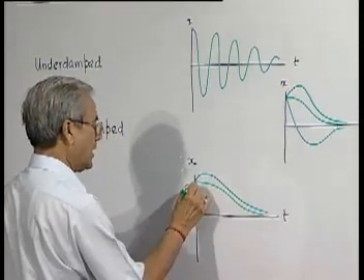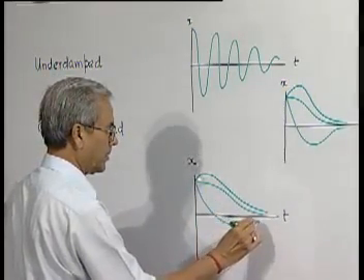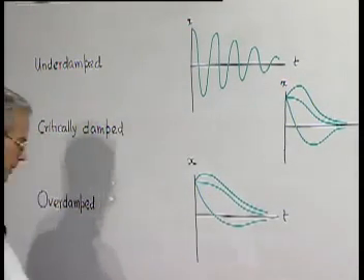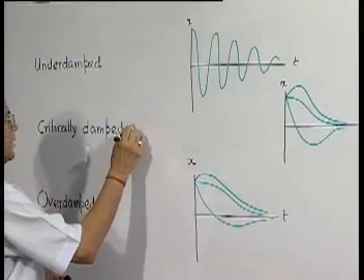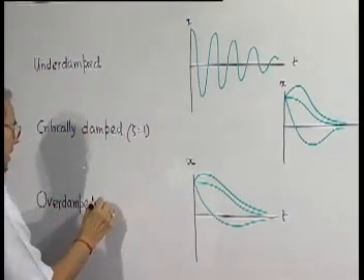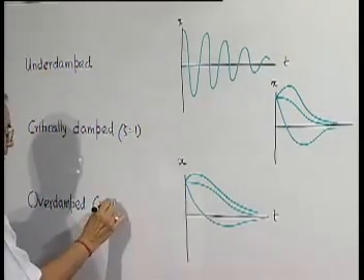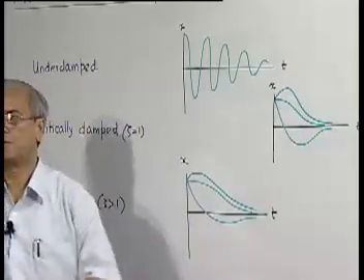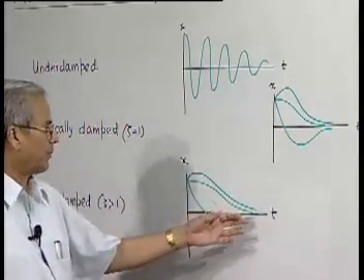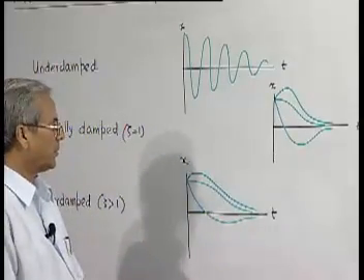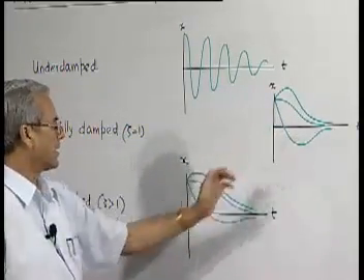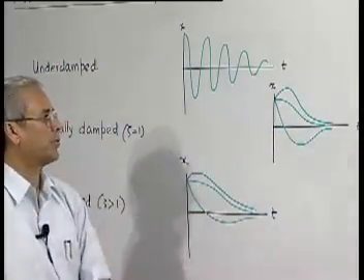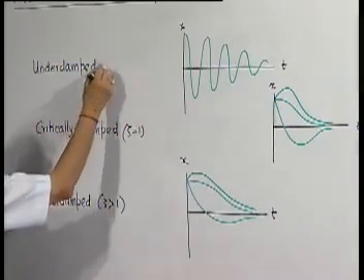And if you push hard enough, so the characteristics of the under damped, critically damped and over damped look similar. Only thing we find is that the decay is slower, or the approach time to the equilibrium position is always longer in case of an over damped system. The characteristics being same, the only difference is that the critically damped system approaches the equilibrium position in the quickest possible time.